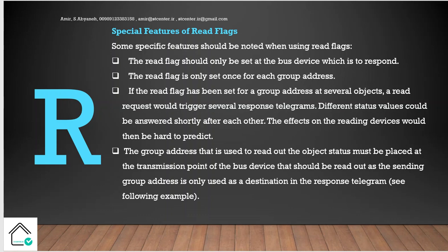The group address that is used to read out the object status must be placed at the transmission point of the bus device that should be read out, as the sending group address is only used as a destination in the response telegram.